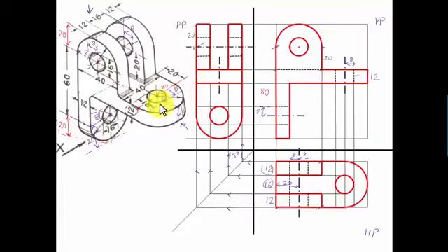Okay, you can say that this axis is at a distance of 20 millimeters from over here, 20 millimeters from here, and then 8 millimeters towards the left we're going to have a hidden line, and 8 millimeters towards the right also we're going to have a hidden line. Okay, so guys, that was all as far as the orthographic or multi views are concerned.